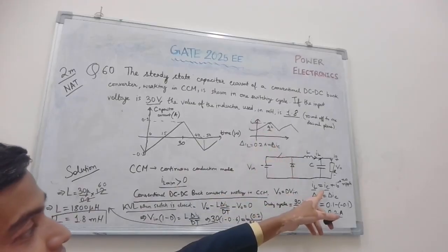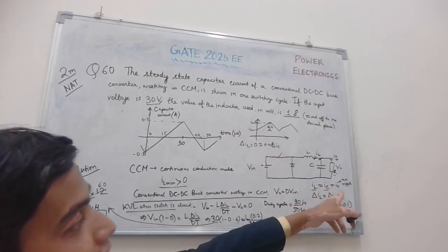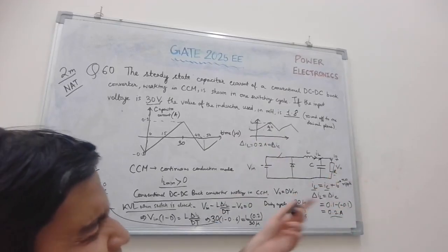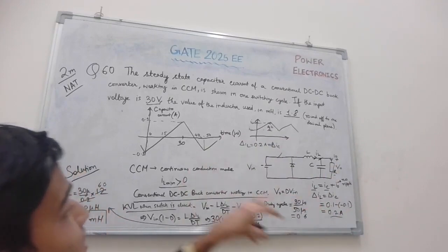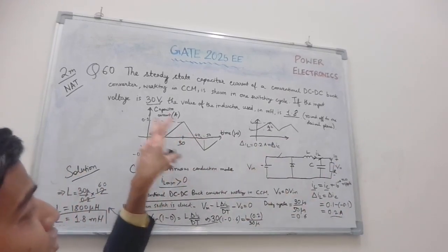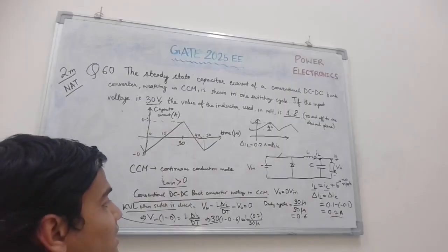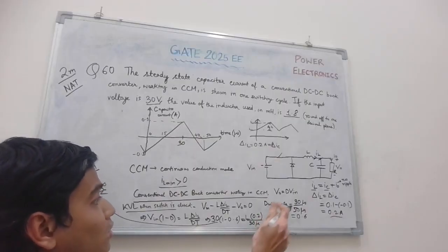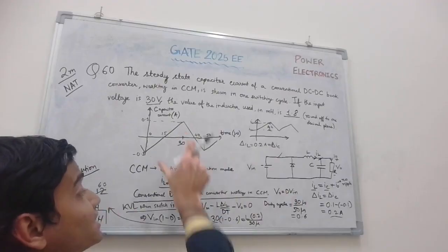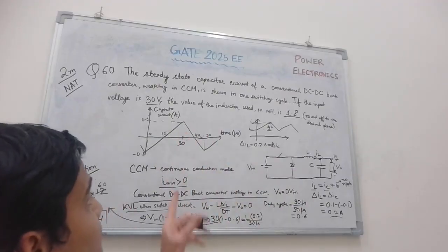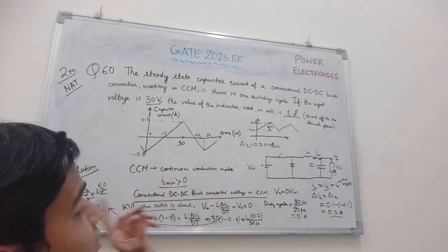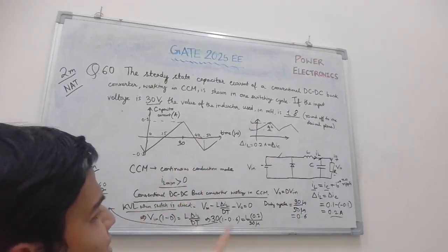The leveling capacitor bank carries the ripple of the inductor current, so the output current will be constant. From that we calculate the inductor current change from the capacitor current waveform, and also calculate for what part of the cycle the switch is closed.